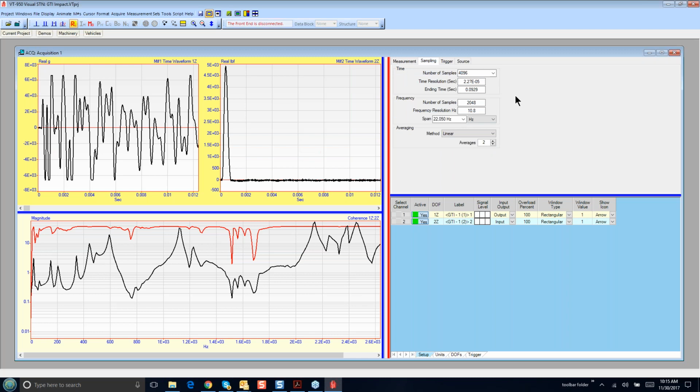And here is the setup for the front end. It's very simple. This is the number of samples that we're gathering from the front end, 4,000 samples, and you can see that the maximum frequency here, what we call F max, is at 22,000 hertz. So that's where the sound card will sample the data for us. Okay, we're ready to go.